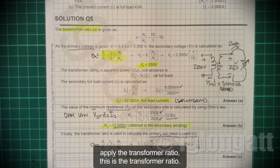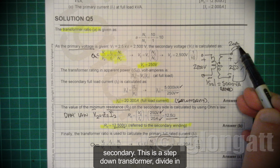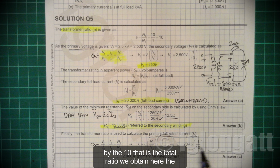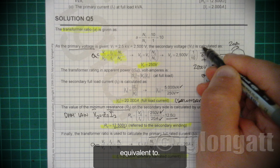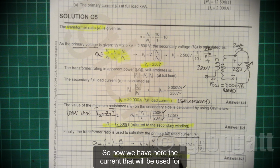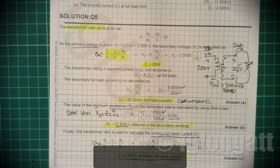Dividing the 20 amps at the secondary by 10, which is the turn ratio, because this is a step-down transformer, we obtain the solution: the primary current in this transformer is 2 amps. So now we have the current that must be used for designing the cable that will be used on the primary side.